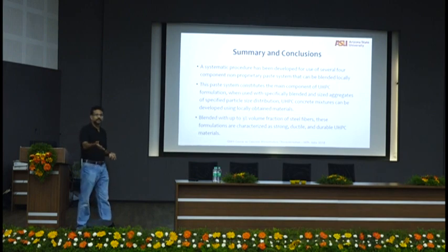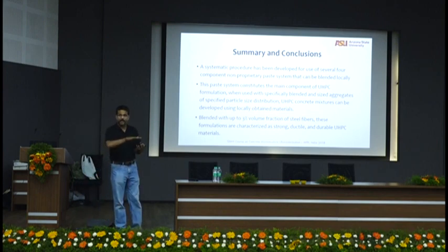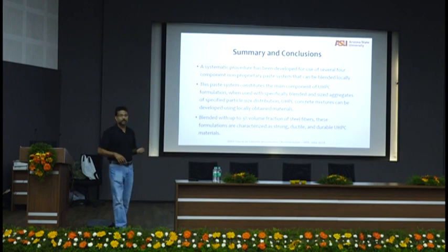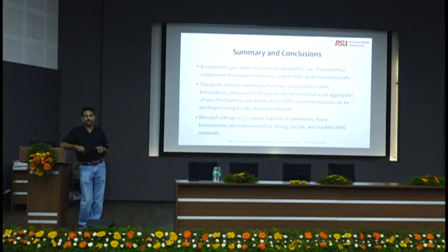You can't just stick it under any compression testing machine and test, because the flatness affects the performance extremely strongly. So you have to really level the surfaces, and then you have to do the test on a strain control system so that you can get the entire stress-strain curve. So it was implemented, and it's one of the first non-commercial UHPC bridge decks that has been implemented in the US, and at much lower cost. Okay.